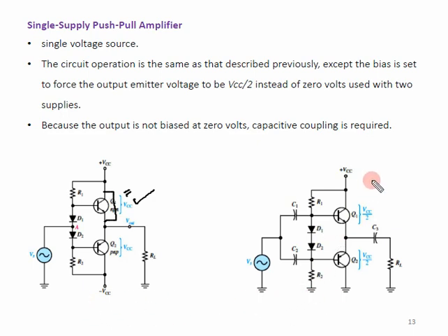Now coming to the modified version, by modified version I mean only a single supply over here. Remember the point, let's suppose this was point A. Now we cannot say that the voltage over here is 0. Why? Because this is VCC and this is at 0 volts, so the two circuits would not cancel each other's effect to give a resultant voltage of 0, as in this case.